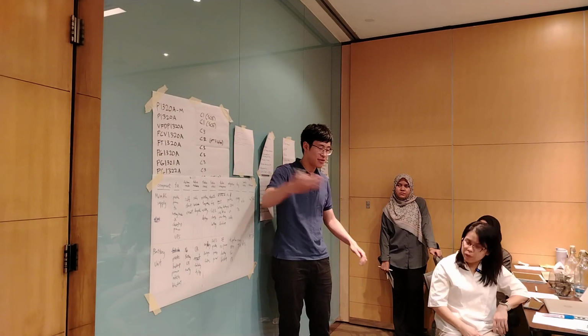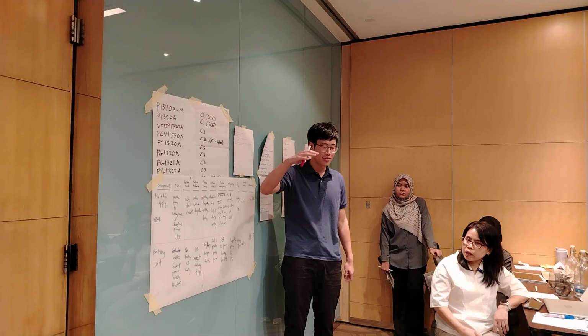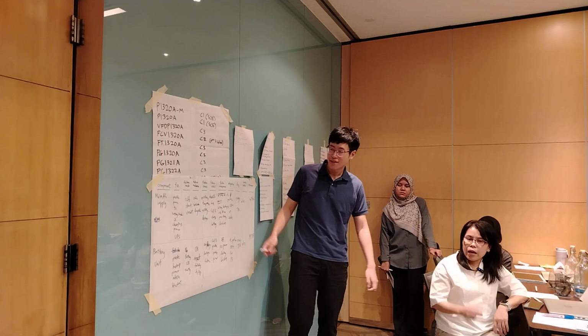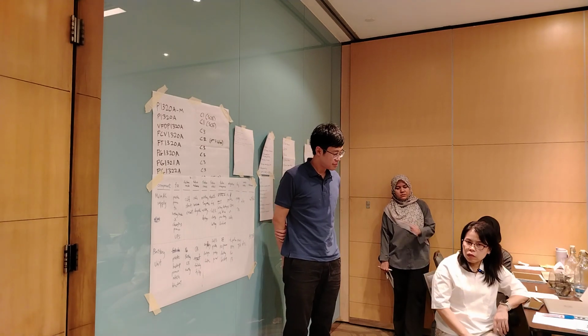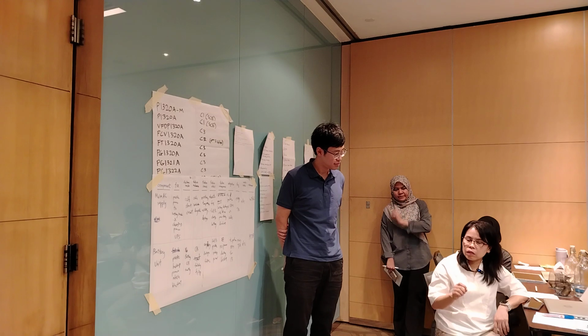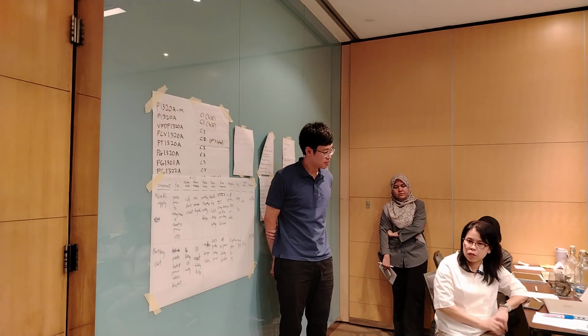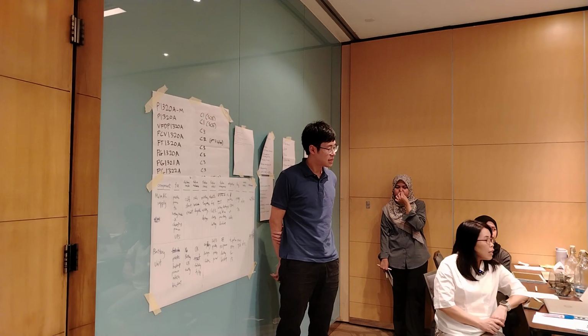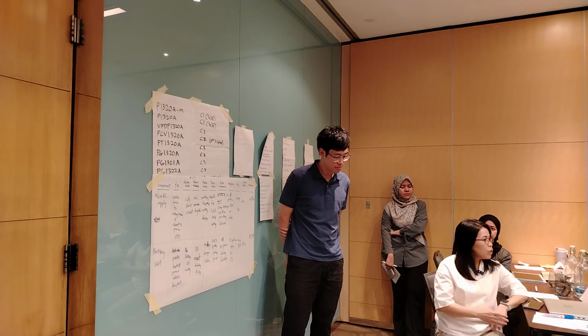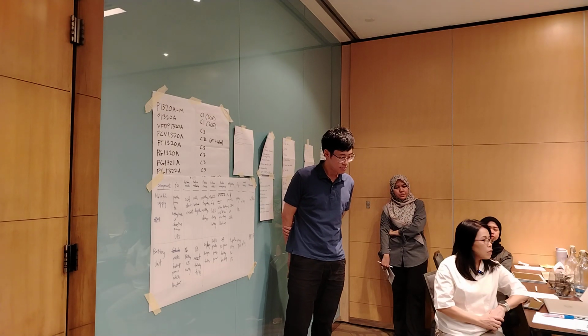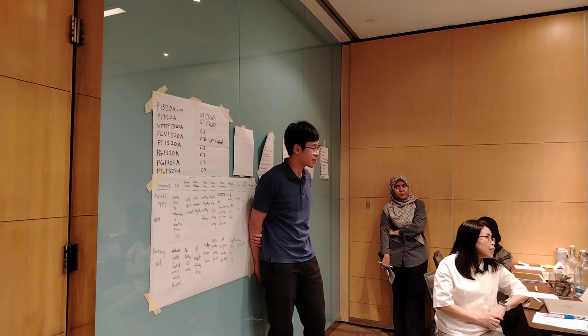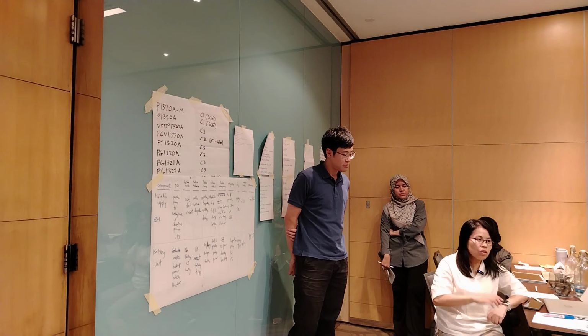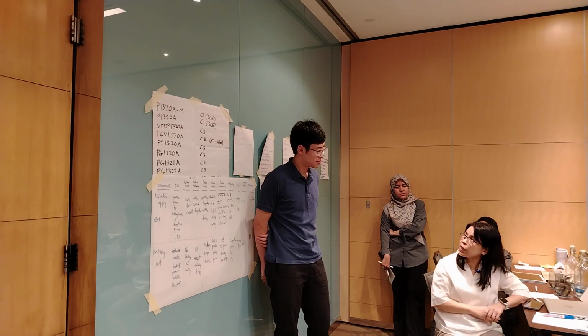Inspection, we just open the door and see if everything is okay, is everything running. And also how you ensure that the UPS is charging the battery. How frequent do you need to do that? Weekly. Make sure that the UPS is charging the battery. That one I didn't see here.